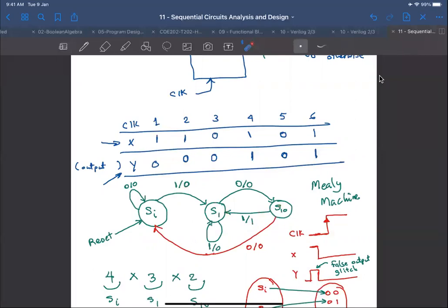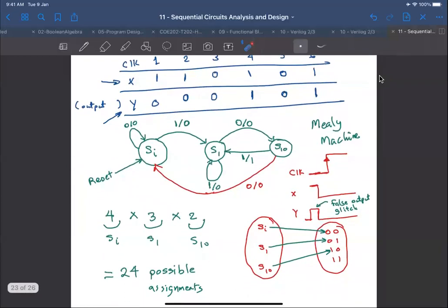For example, in this example, we have 1, 0, 1, and then followed by a 0, 1. So this sequence here and this sequence here share this 1 here. If overlapping is not allowed, then we wouldn't drive the output high here. So overlapping makes us drive the output high whenever we observe the sequence, even with overlapping. So this is a Mealy machine.